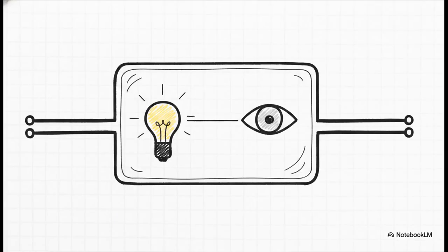And these light-sensitive switches, they are literally everywhere. They range from basic light-operated relays to incredibly clever components called optocouplers. An optocoupler actually places an LED and a phototransistor inside a single sealed black box. It uses light to electrically isolate 2 totally different circuits, letting them communicate perfectly securely without a single physical wire bridging the gap between them.